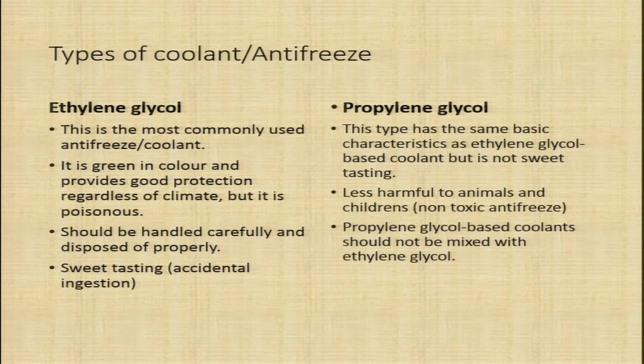Propylene glycol has the same characteristics as ethylene glycol, but is not sweet in taste. It is less harmful to animals and children. Propylene glycol based coolants should not be mixed with ethylene glycol. But in aviation, in aircraft engines, the most commonly used coolant is ethylene glycol.